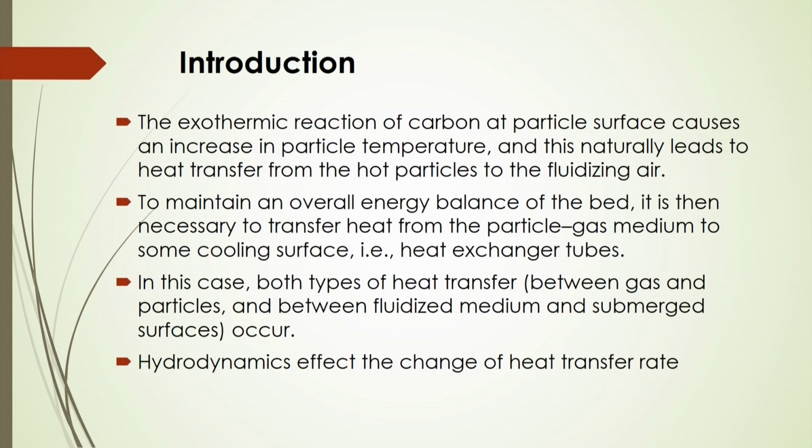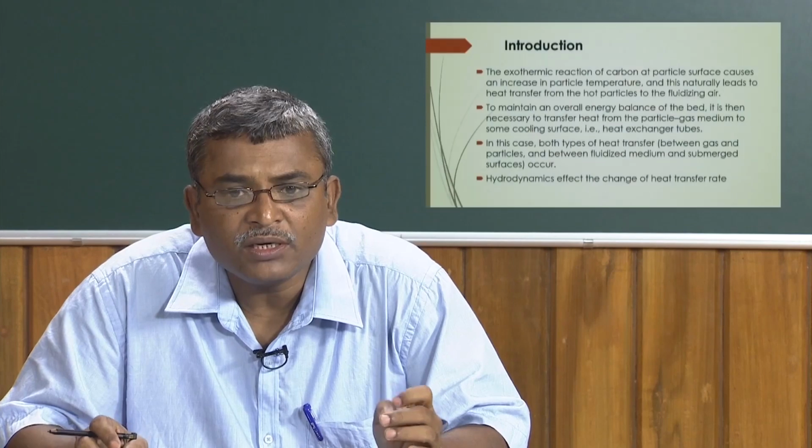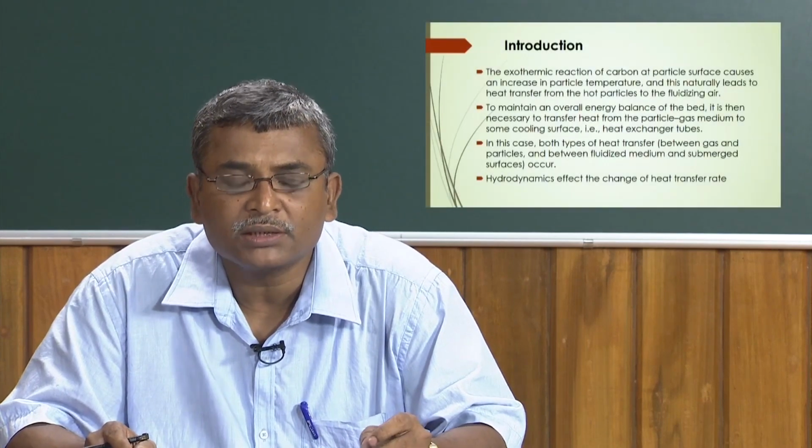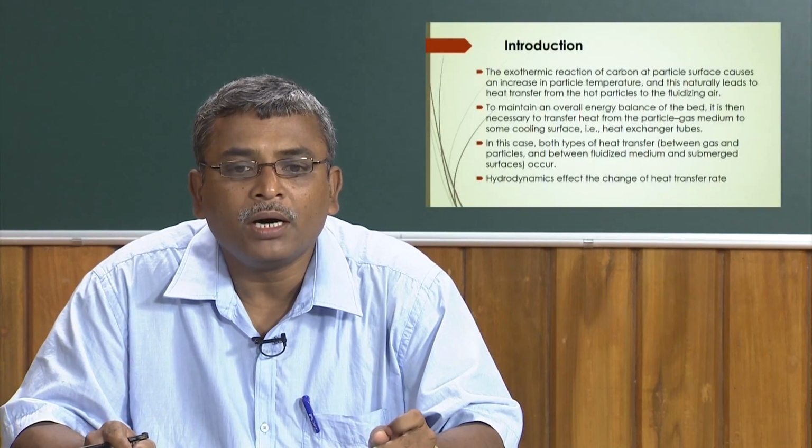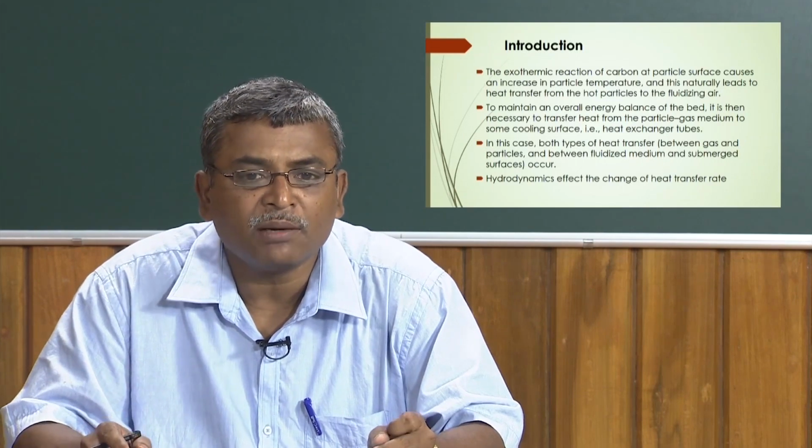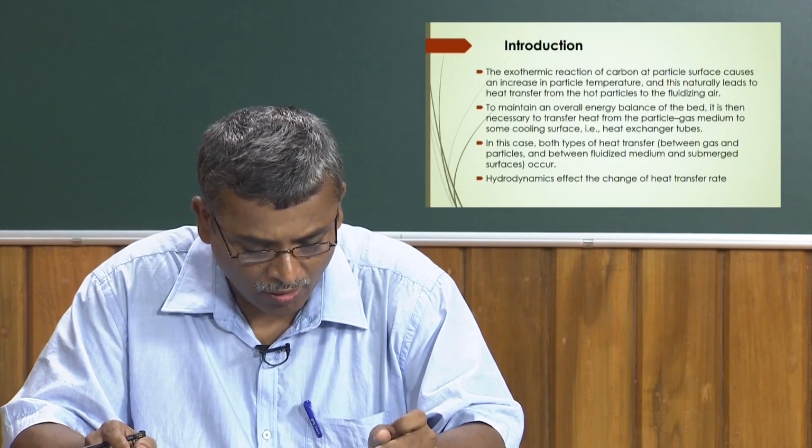So, to maintain an overall energy balance of the bed, it is necessary to transfer heat from the particle gas medium to some cooling surfaces, and to do that, maybe some heat exchanger devices can be used for this purpose. Now, in this case, both types of heat transfer, between gas and particles and between fluidized medium and submerged surface, will occur.